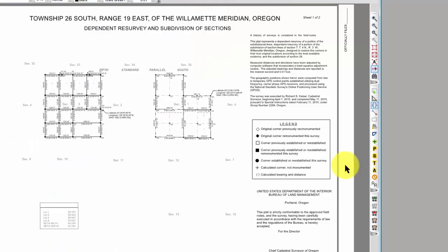So let's take a look at kind of what's involved with a public land survey, and then just jump in and start taking a look at these. So public land surveys say we're going to do everything in true bearing so that we can account for convergence. So as we change latitudes, we get more convergence as we go north. In the southern hemisphere, as we go south. So we're working with true meridians along the way.